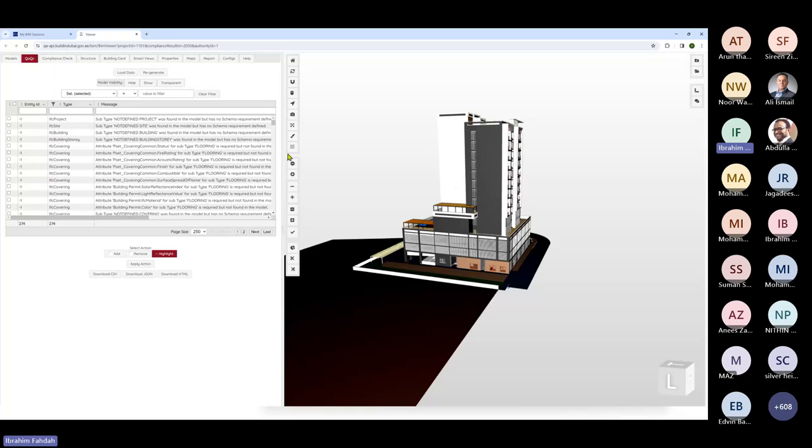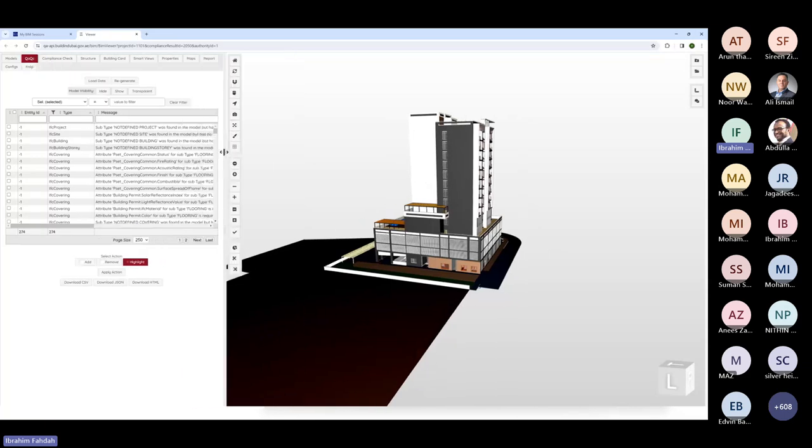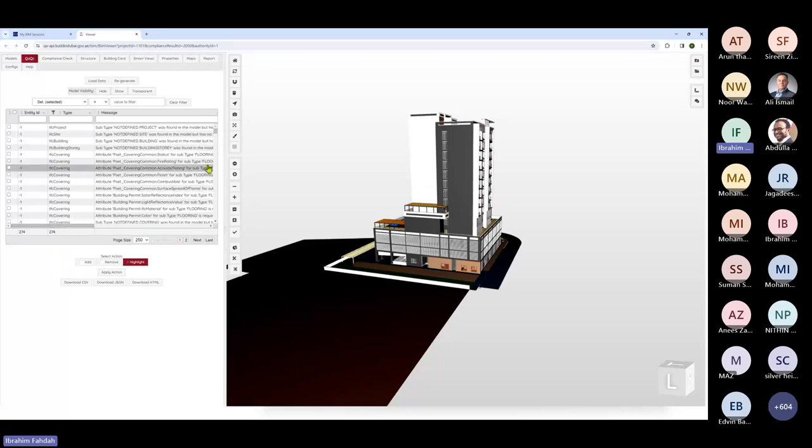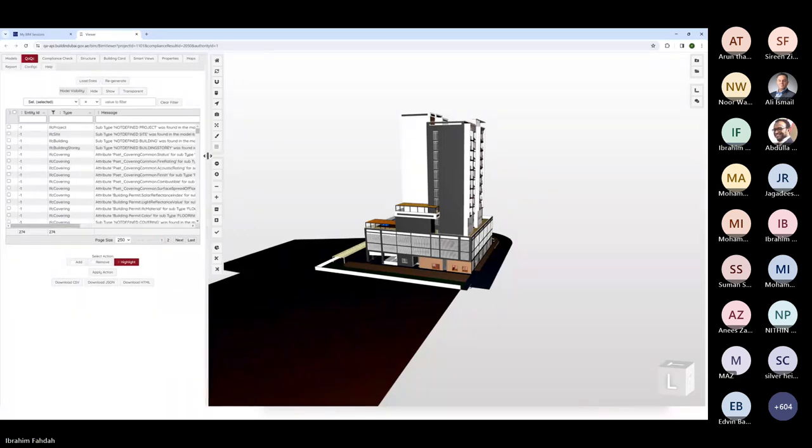In this case, you should not submit this model unless, of course, it's preliminary or for other reasons DM might accept this. But typically, you should go back to the BIM authoring tools, rectify the issues and the information, and upload a new version of the zip file, and make sure it's all clear that there are no QA/QC issues. So this is the second thing.